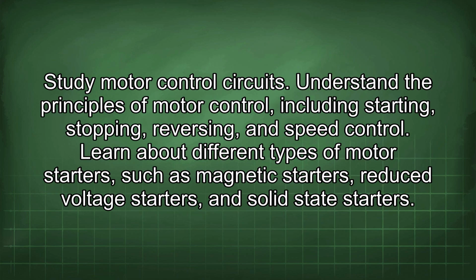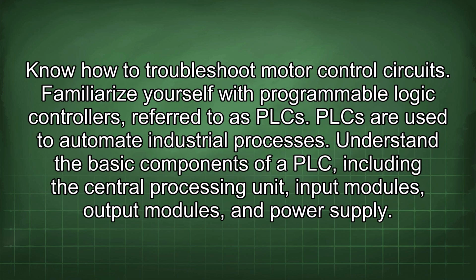Study motor control circuits. Understand the principles of motor control, including starting, stopping, reversing, and speed control. Learn about different types of motor starters, such as magnetic starters, reduced voltage starters, and solid-state starters. Know how to troubleshoot motor control circuits.